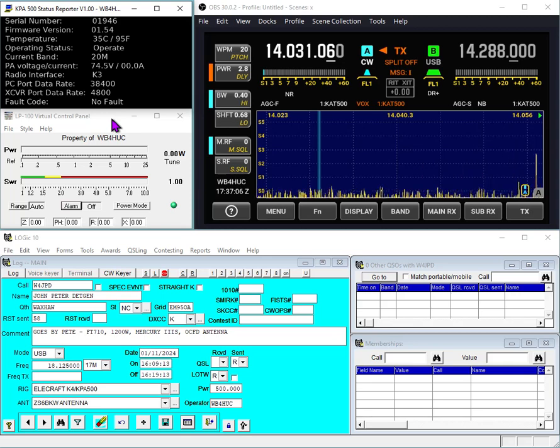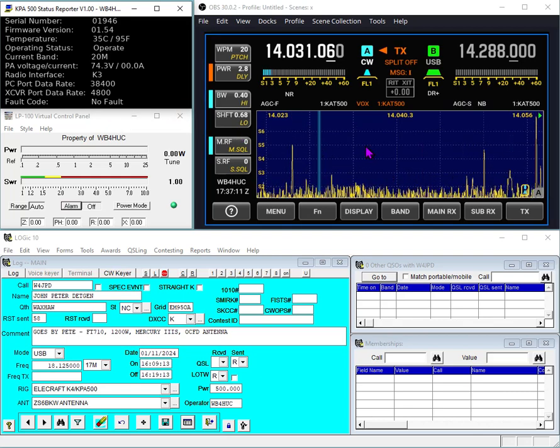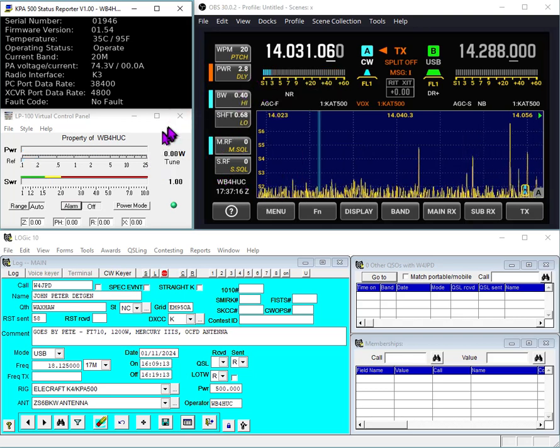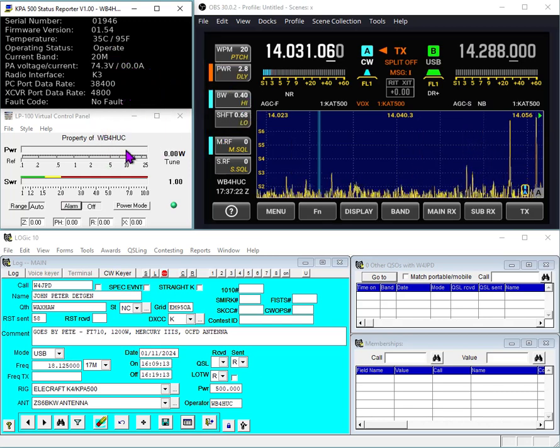So if I go back to antenna 1, you saw the signals come up, and we're putting out about 2.3 watts. Here we say 2.8 watts. So the amplifier is in operate mode, but it's not doing anything because the key line is interrupted. So as I understand it, there are 2 ways to get the tuner to enable the keying line. One is if you have software that can send a command to the tuner to tell it to enable a keying line. I don't have that. The other is to initiate a tuning cycle, and that will do it.